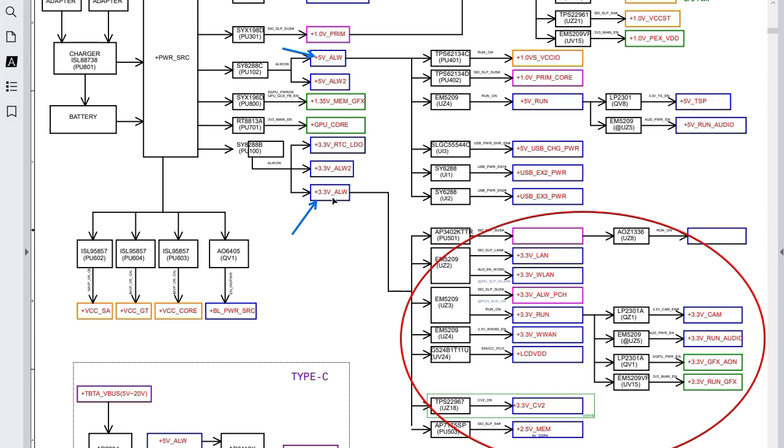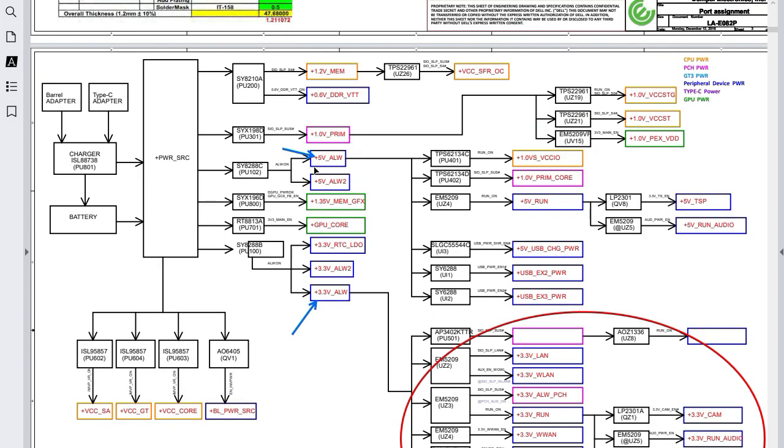So always when you get a failed motherboard or a dead motherboard, you should check whether you have this voltage or not. Also, another main voltage basically is plus 5 volt always. Also for plus 5 volt always, if this voltage is missing, we cannot get also these voltages, as you can see for many basically peripherals in the motherboard, including, for example, the VCC for input output for the SIO.